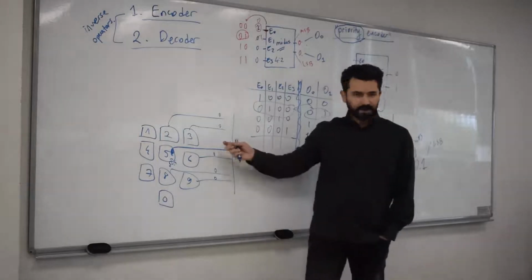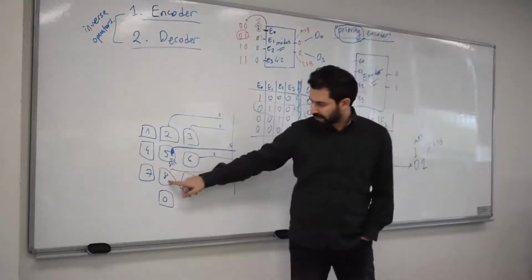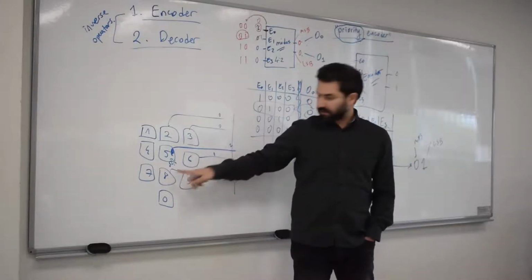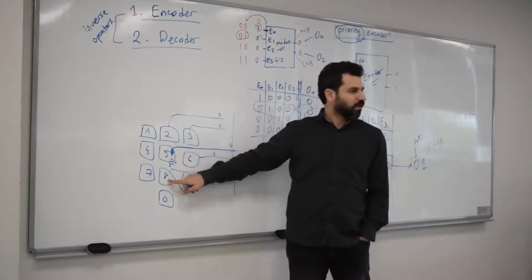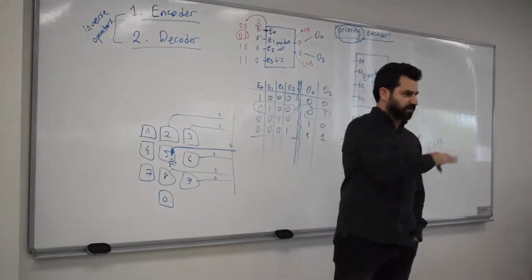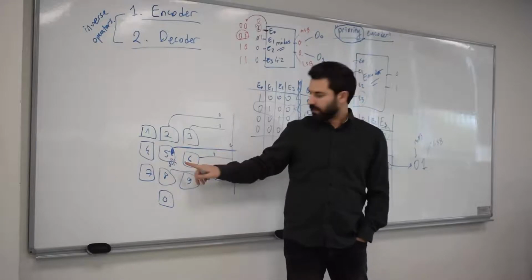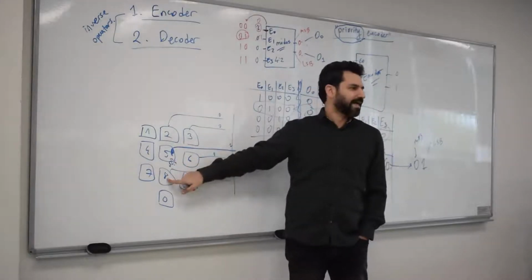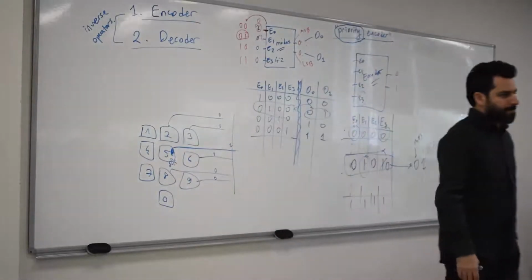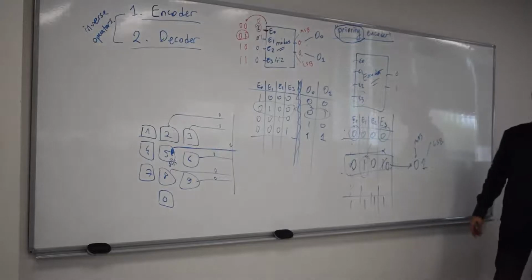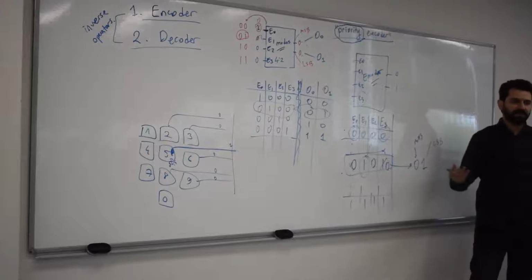But okay, if you think about the 10 inputs case, in this case you would take 8, because 8 is a bigger number, so the most significant bit of 8 is going to be closer to the left hand side. So if you push 5 and 8 in any order you like, the priority encoder will get it as 8, not 5. It's not about time, it's about the most significant. So it takes the bigger number in the decimal domain. Okay? It takes the bigger number.